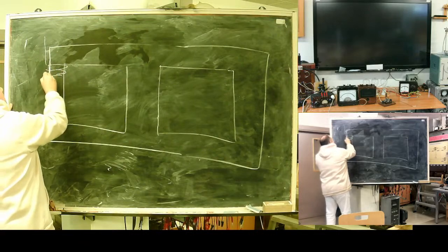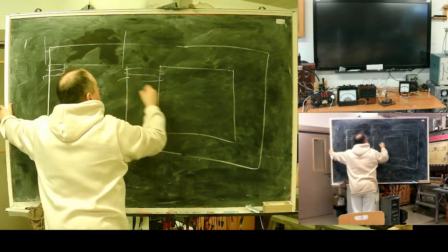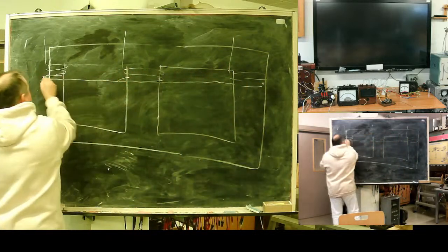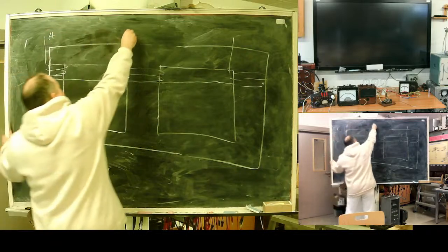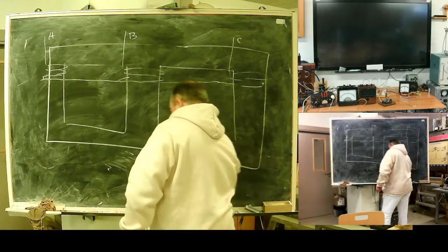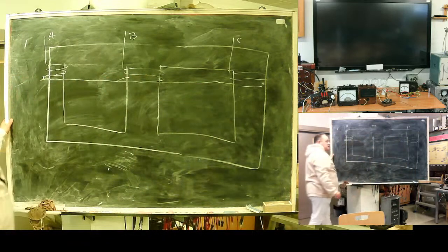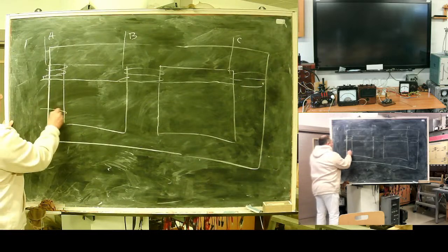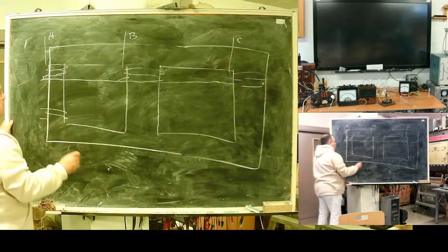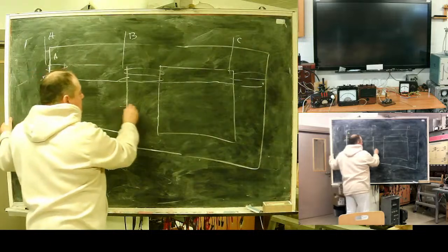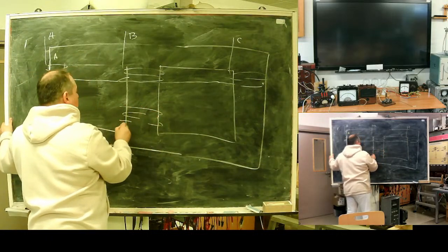The primary winding is ordinary. On the primary side, everything is simple: a simple delta connection, A, B, C. But the secondary side is something special. On the secondary side, each winding is constructed of two parts. One occupies its own leg. The second one sits on the neighboring leg.